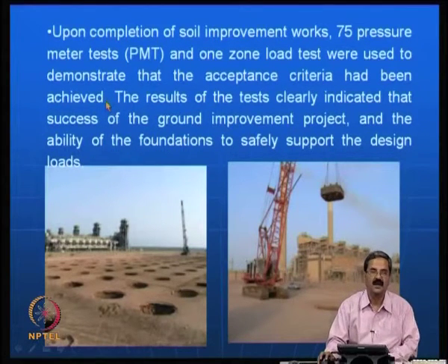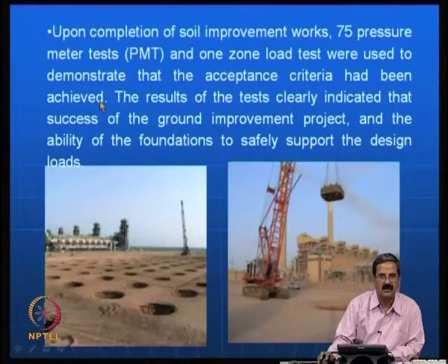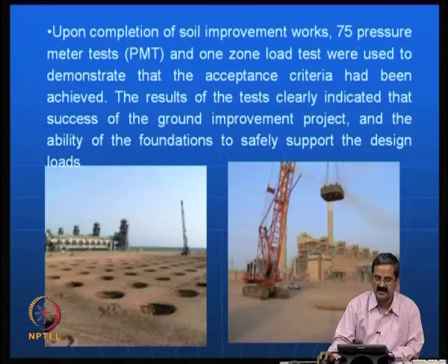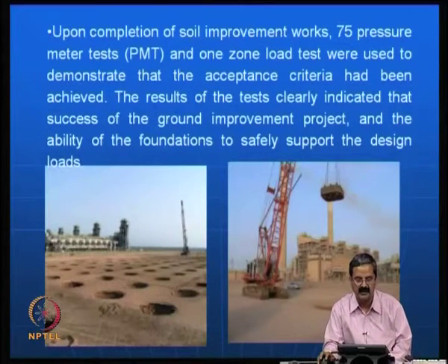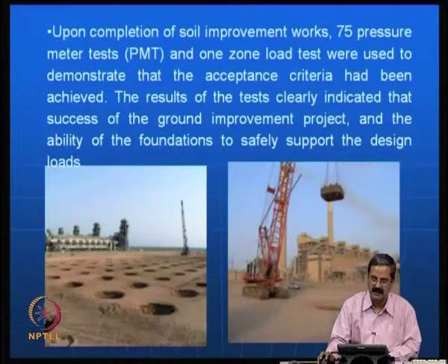The acceptance criteria are the bearing pressure and settlement. You can calculate the bearing pressure and settlement using the pressure meter test, which gives a parameter called limit pressure. Limit pressure is related to bearing capacity, and settlements can also be calculated. So the acceptance criteria of settlements and bearing capacity is met using this. The results clearly showed the success of the ground improvement and the ability of the foundation to safely support the design loads.